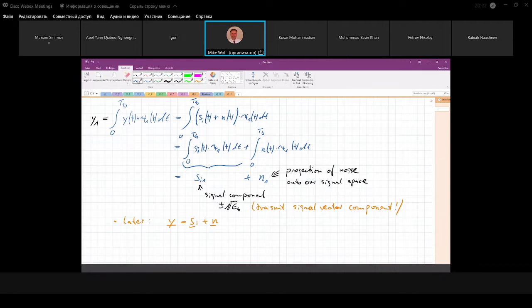This may be a little bit difficult, but we solved the following result if we take a look at the statistics of the noise. The noise before our detector is continuous time AWGN, so additive white Gaussian noise. This is still additive, but now in the digital domain. And if we now take a look at the variance, the expected value of N1 squared.